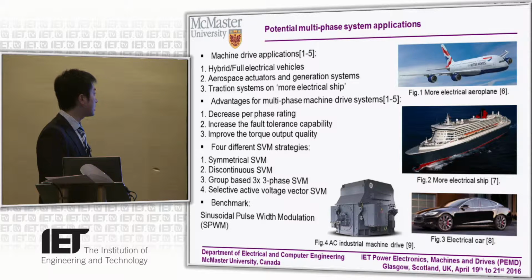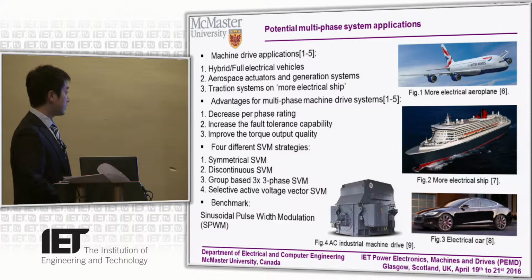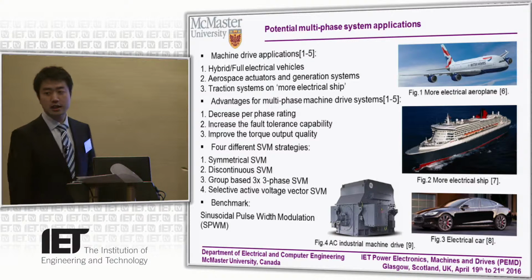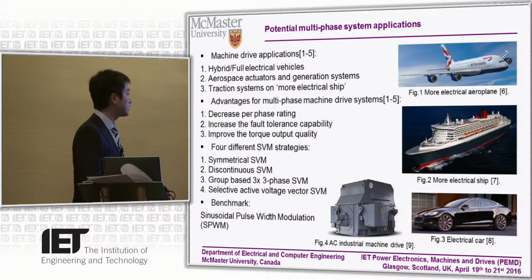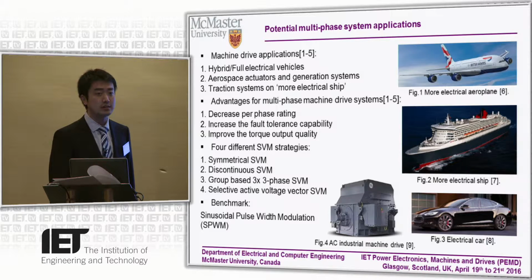The first one is the symmetrical SVM. The second one is the discontinuous SVM. The third one is group-based SVM. And the fourth one is the selective active voltage vector SVM. We also use sinusoidal pulse-width modulation as a benchmark to compare with the different SVM strategies.